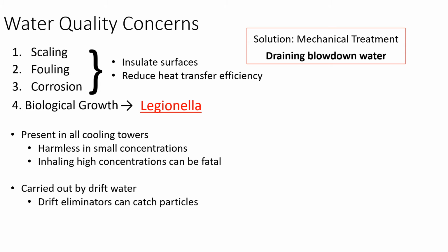Small concentrations of Legionella are harmless, but exposure to Legionella via inhalation can lead to Legionnaire's disease, which is a form of pneumonia that can be fatal. Legionella bacteria escapes from the cooling tower through drift particles, which is another reason why drift eliminators are an important component of the cooling tower.